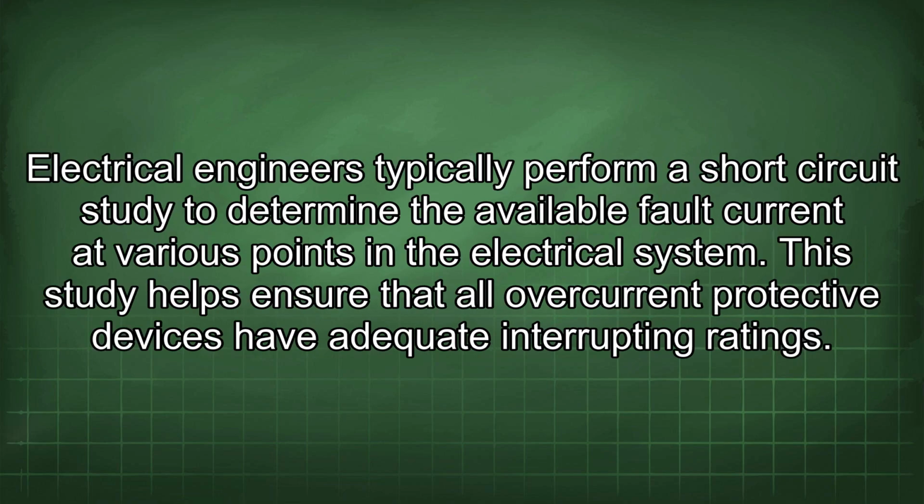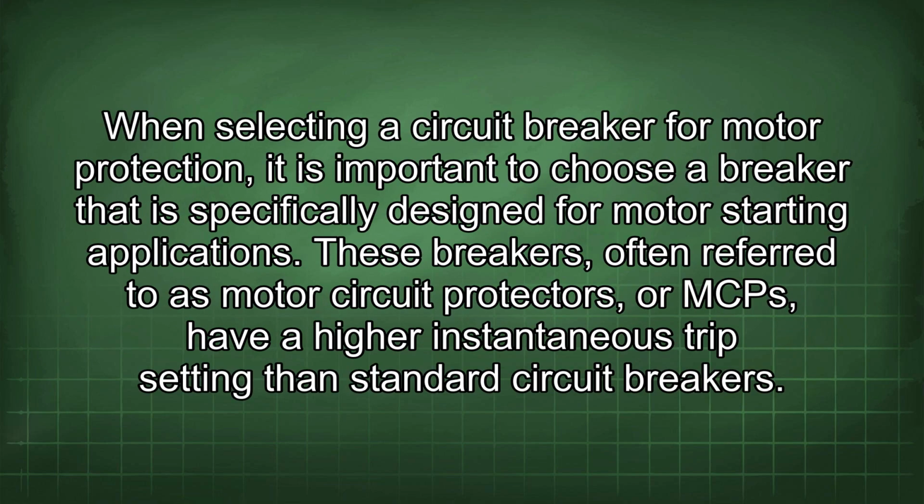Electrical engineers typically perform a short circuit study to determine the available fault current at various points in the electrical system. This study helps ensure that all overcurrent protective devices have adequate interrupting ratings. When selecting a circuit breaker for motor protection, it is important to choose a breaker that is specifically designed for